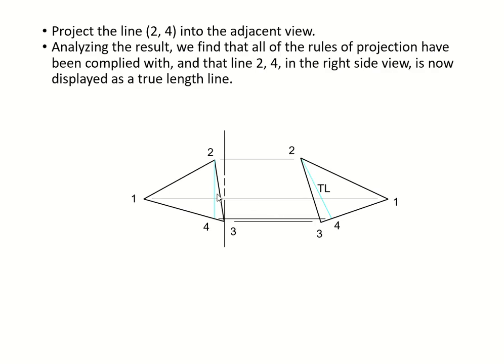And now we're gonna project that line 2, 4 to the right side. Again, don't forget, this is a right side. This is a front, so you're looking at this from this direction, towards it. So when you draw, like that, I gotta draw that for you. So do that in your mind to be able to see it. So when we go point to point, 4 to 4, we're gonna get like that.